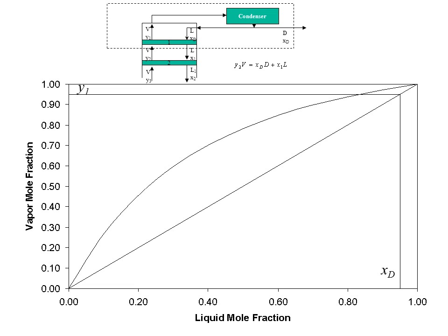Now we're going to look at how to solve this problem in determining the number of stages above the feed stage graphically. On our graph here we have two lines, one being the y equals x line, and the second is a suitable vapor-liquid equilibrium curve. The one you see in front of you was generated using Raoult's law. However, different models are available depending on the nature of the liquids and vapors in equilibrium with each other.